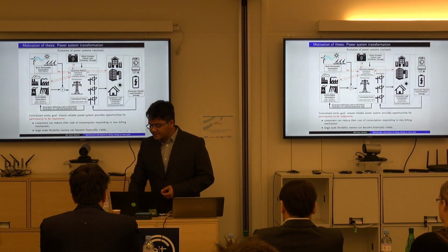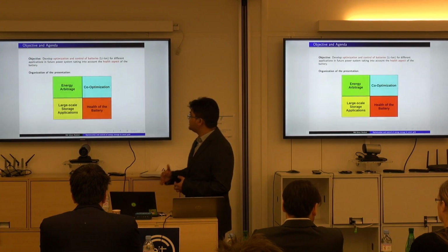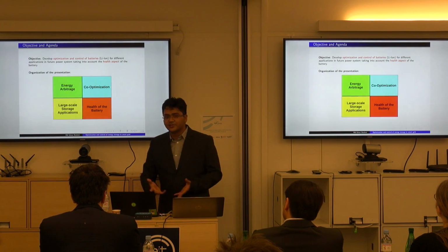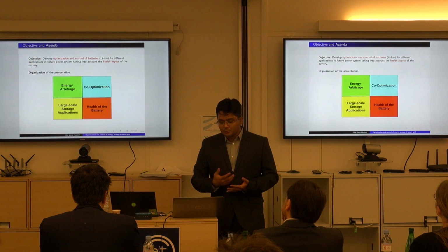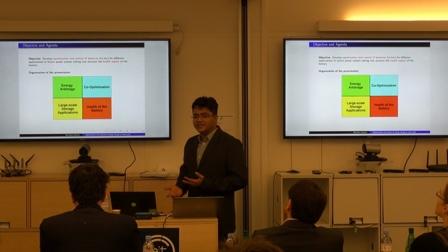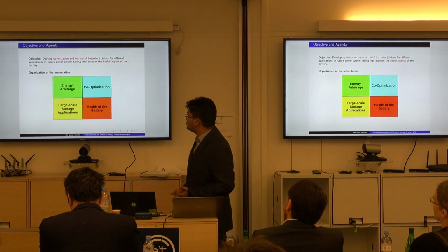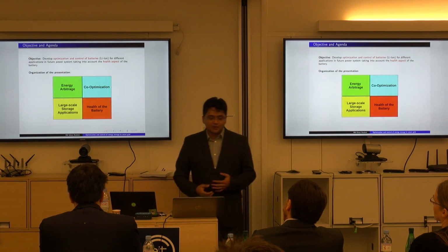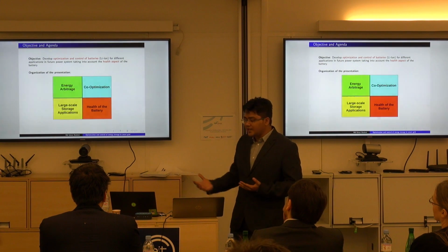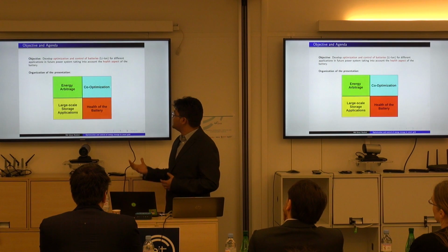So in this thesis, we talk about energy storage providing different services. We develop optimization and control algorithms specifically for lithium-ion batteries. The motivation for choosing lithium-ion batteries here is that presently more than 80% of batteries in the power grid are lithium-ion, so that motivates us to do that. Now, lithium-ion batteries have life constraints, so they degrade over life, and you would like to take the health aspect and integrate that with the optimization and control.